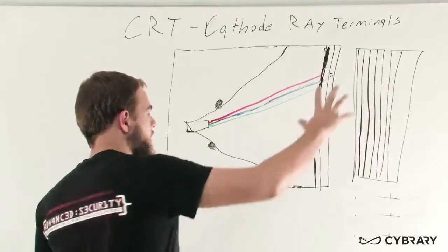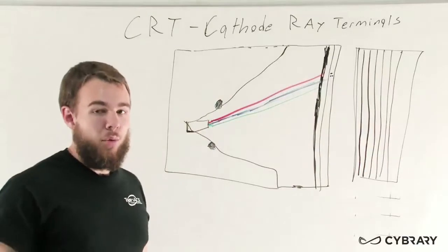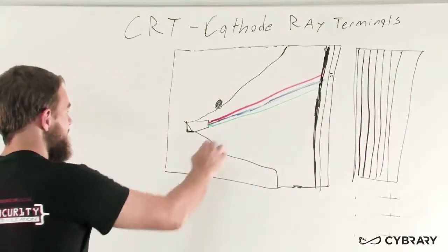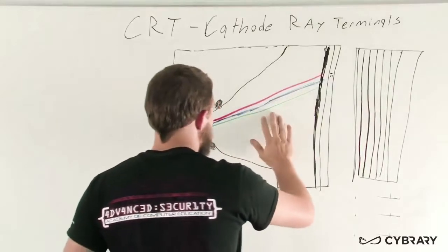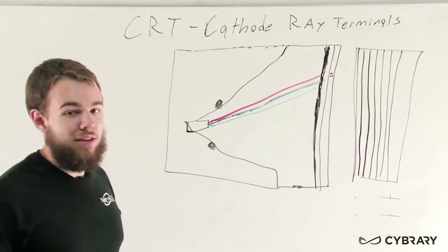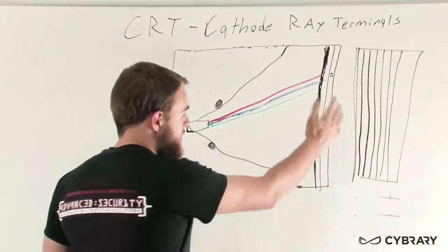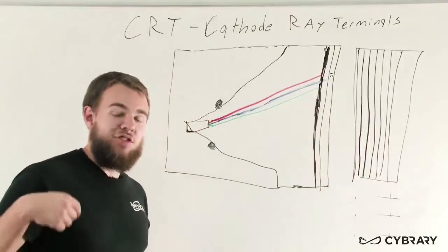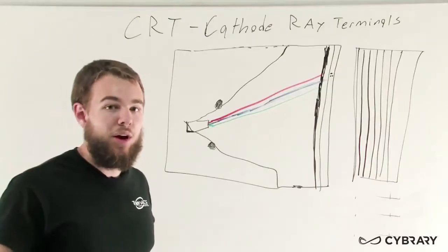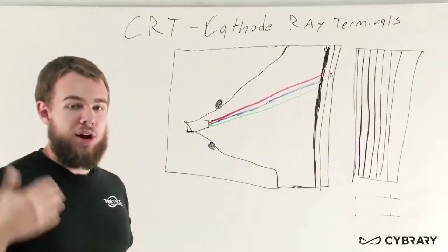Now, we talked a little bit about how magnetism on our shadow mask or on our slotted mask can cause issues when we're trying to display a picture with our CRT monitor. These electron beams are actually moved by magnetism. The individual particles, if this mask is getting magnetized, can become deflected and start going in directions where they shouldn't. They can become stuck to it when we really want them to pass through, hit our screen and illuminate it.